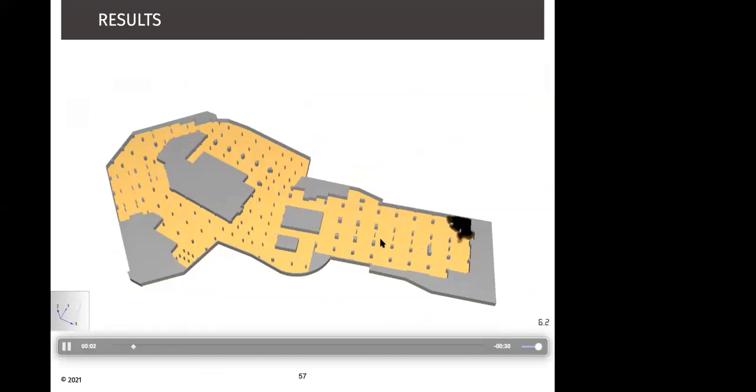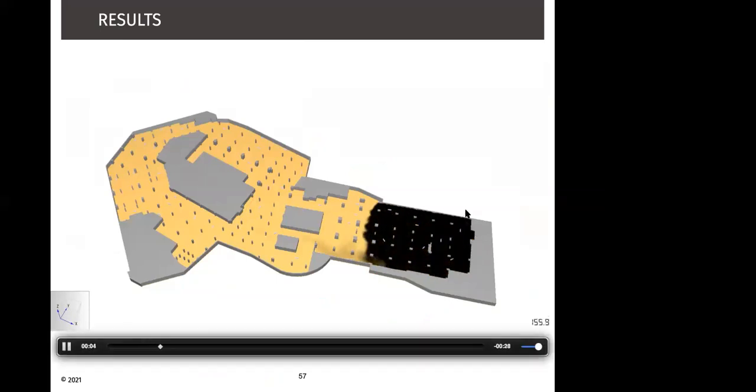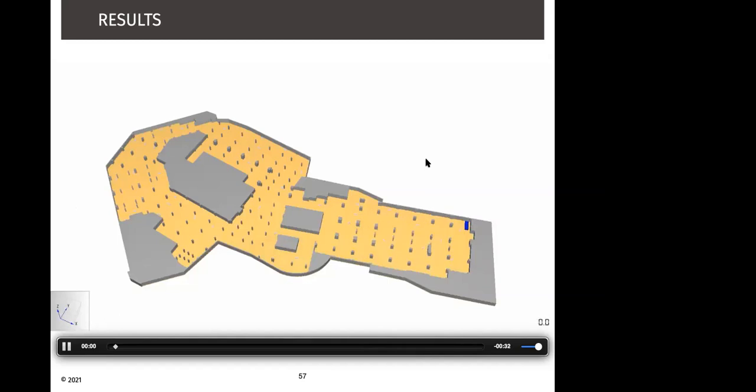So why that's important is, if you have a fire in this area, because of that wall of air being formed, very little smoke is actually being pulled into the exhaust fan. The fresh air is only being pulled across the car park and into the exhaust shaft. So the smoke actually accumulates in this area. Even after 30 minutes, the smoke has remained in that area.